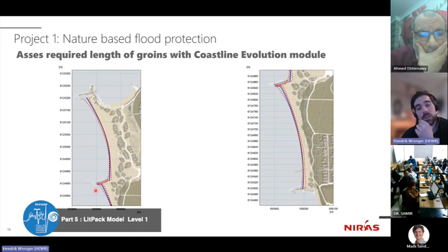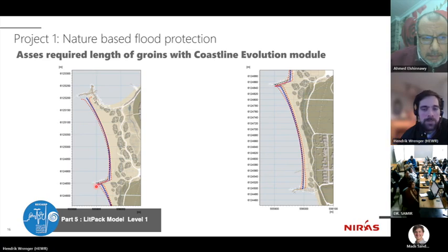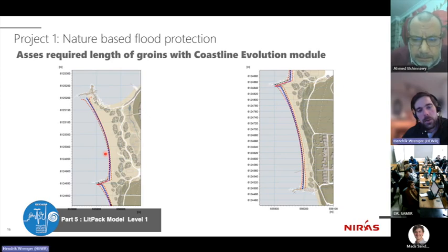And then again, this was an application where the model formulation in the coastline evolution structures part was made for, because it's semi-empirical formulations of some sheltering effects, etc. If these structures became huge, maybe way exceeding the breaker line, or if there were too many, so that the re-establishment of longshore transport some certain distance along the shore from the one structure we have already the next one, then we would violate the model assumptions too much, and we could not use this tool.